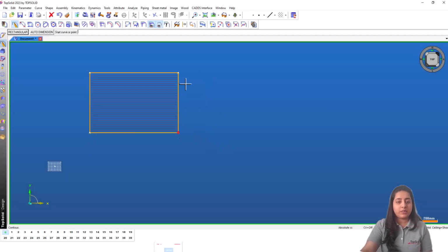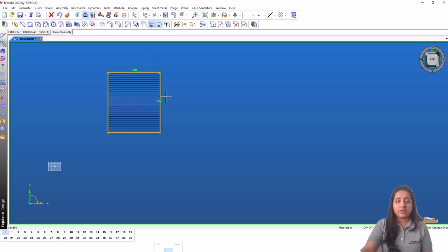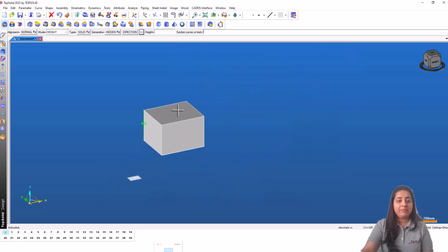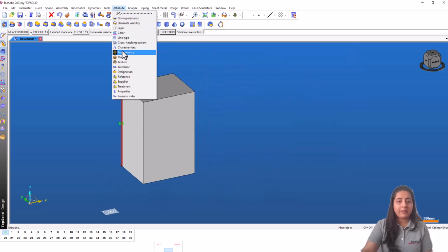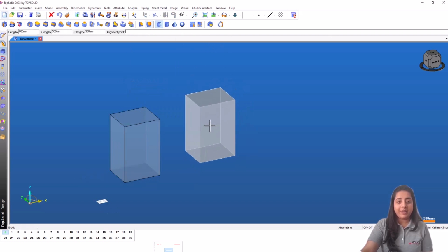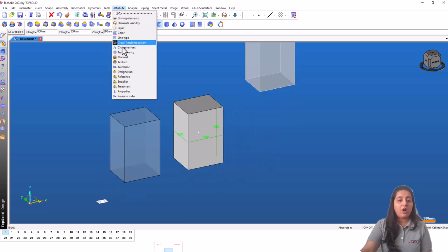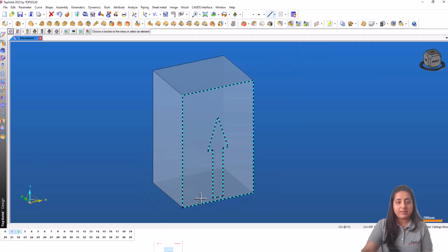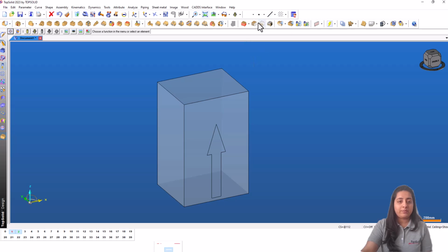Before we jump into the usage of constraint block, we need to create a boundary for our unit. This can be achieved by different methods. Simply by making a rectangle and extruding it to make a block like this, or directly making a block using a shape context with the same dimensions, or by creating a driver block like this. Creation and usage of driver block is explained thoroughly in another video. Please check it out on our channel. As far as constraint block is concerned, any of these methods can be used according to your convenience. I am going to use a driver block here.